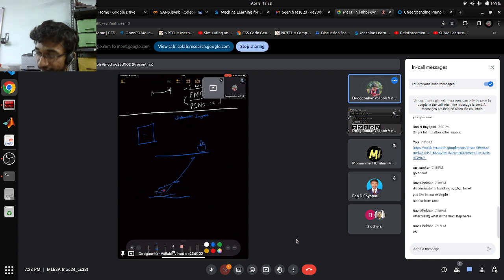One way of doing this is to connect a tether from the ship down to the bot and transmit that entire data. But in such a case, there is a limitation on how much the bot will be able to explore around, right? So in such a scenario, you might want there not to be a tether. You want the communication to be wireless, but if it is wireless, then the problem that comes is the bandwidth.